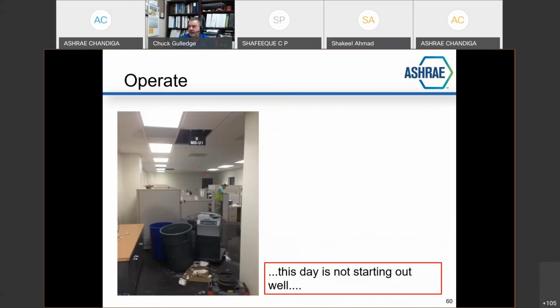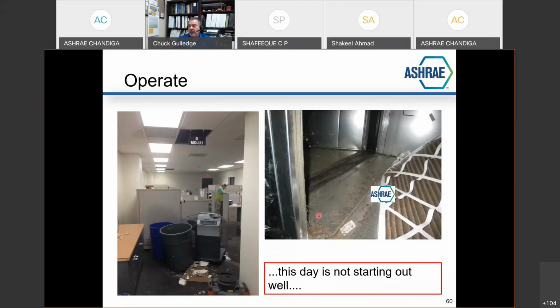This day is not starting out well. You can imagine with all the water you see on the floor and all the cans that are collecting the drips and the fact that a ceiling tile is missing now and an expensive copier is underneath that, this is not a good day for somebody. And I got called to the carpet to explain myself: what were you doing? Why does your system not work very well? And it all came back to an air handler sitting above this space where the filter had gotten so dirty it had actually collapsed, and this was the position it was found in.